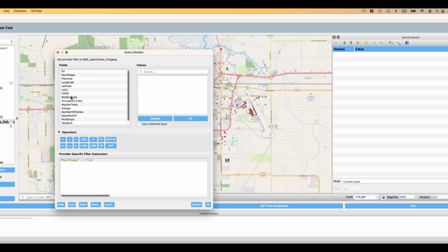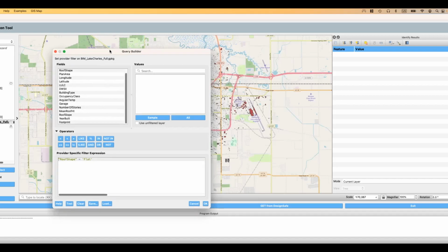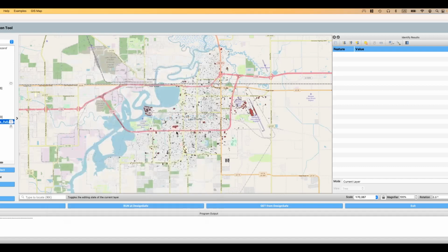And we could go to different types of building classes, occupancy classes. If I included, say, the census information here, we could look at low-income houses, run those, and then compare how they fare versus high income houses to see the disparity between different types of the population. So it's quite powerful: you can go through the different types of fields, choose the assets you want to run, and then send those forward into an analysis.